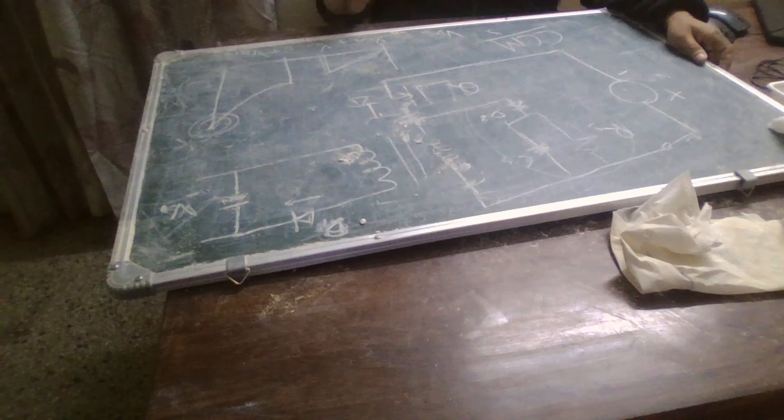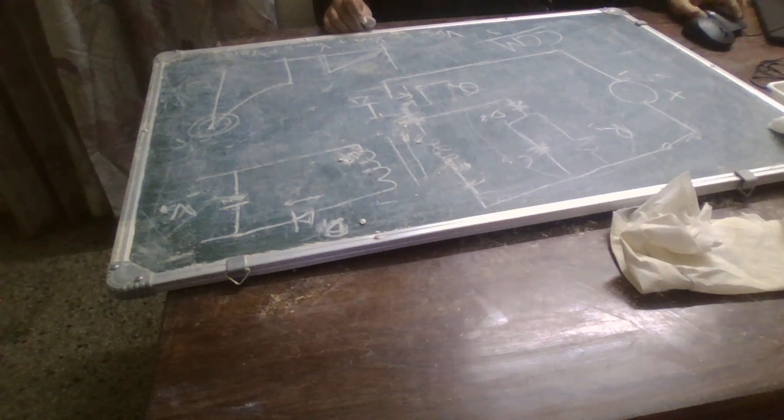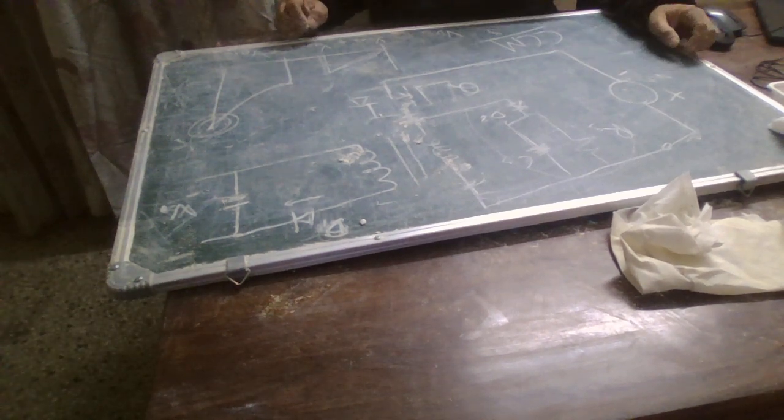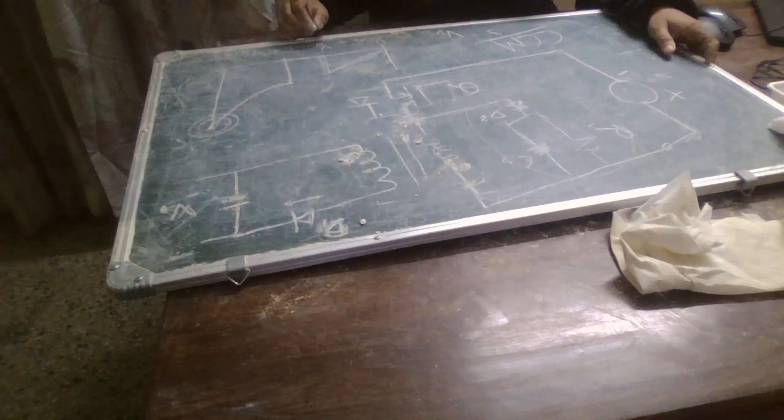The flux does not get cancelled there. So that's why we use an air gap magnetic core, which reduces the chances of magnetic saturation, and this air gap is inserted in the limb of the transformer core. Okay, so the air gap doesn't change the flux density value, it only increases the magnetic field intensity. I will cover the different kinds of cores used to design the transformer, SMPS cores, and at that time I will include an air gap core also.